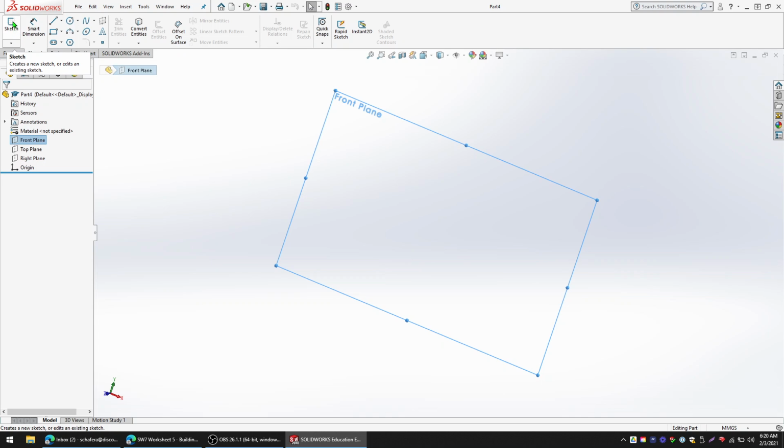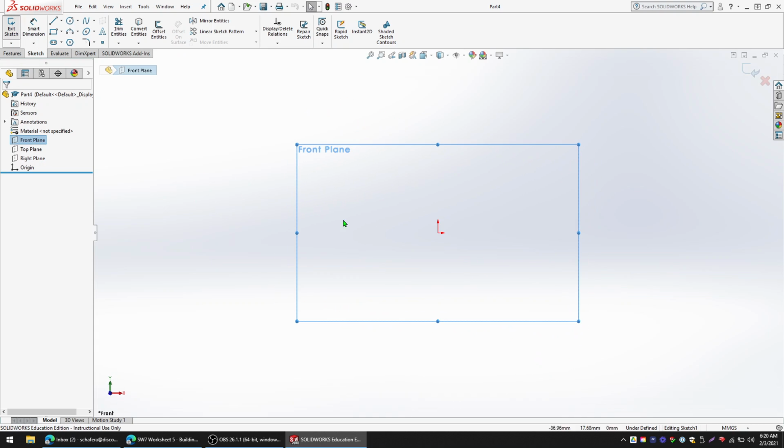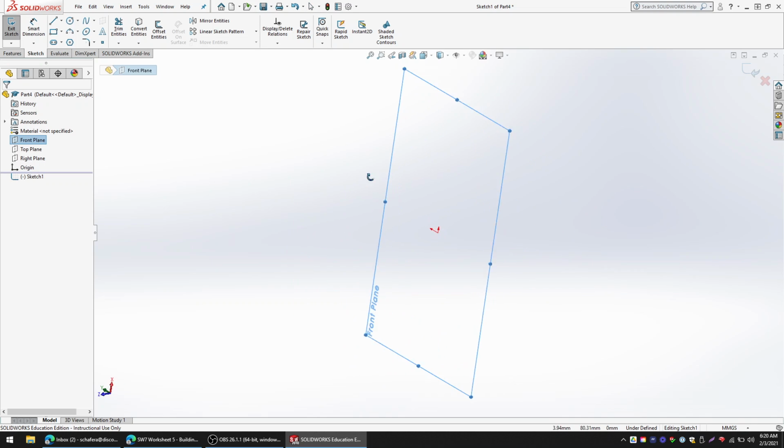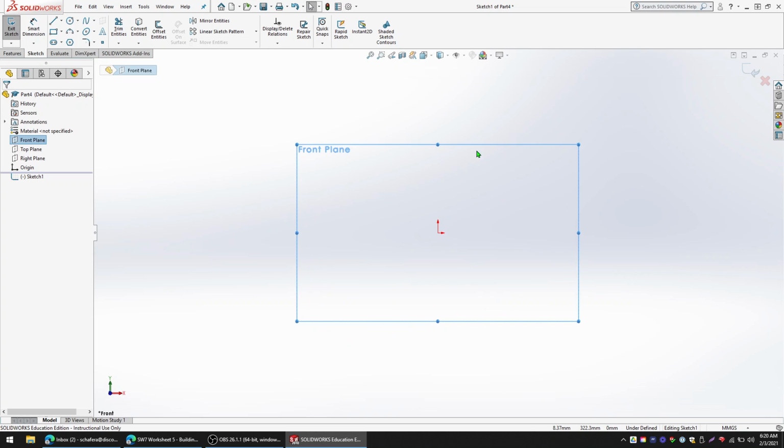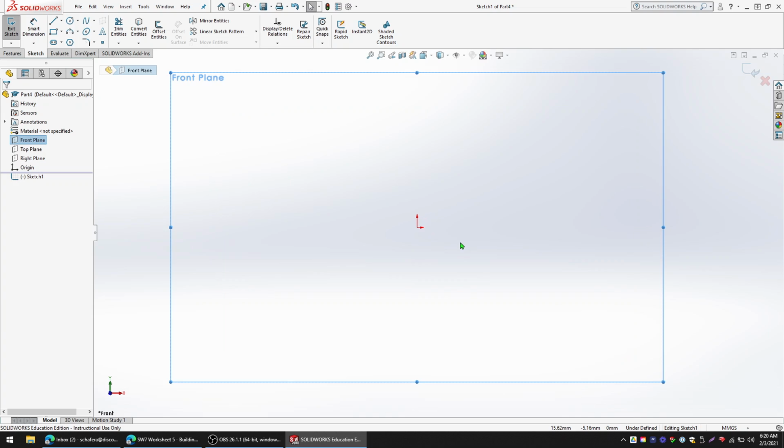Okay, remember this is all step one. We're going to create a new sketch here. So again, click on your front plane, create a new sketch. That should rotate so that you're looking straight at this. It's not like curved or on an angle or anything. If it is still, then you want to hit Control-8 on your keyboard, and that will rotate it back for you.